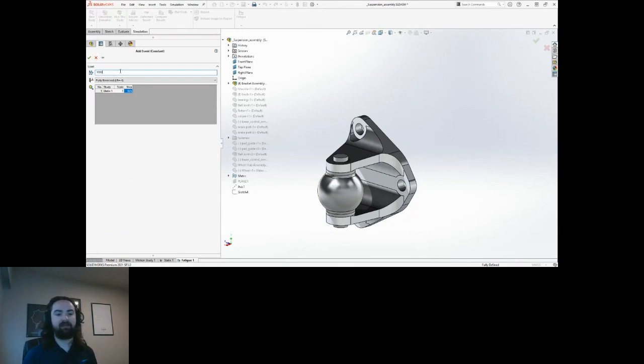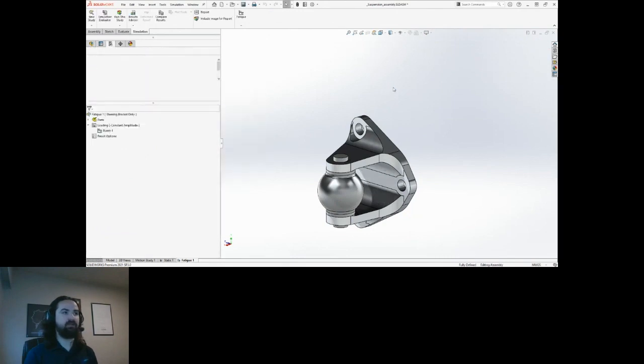And I did a bit of math here, and based on the number of corners at each track, the number of laps completed each race weekend, and the number of races during a full Formula One season, the steering bracket will have to undergo roughly 100,000 cycles. So I'll plug that value in, and that's all the information that is needed for this fatigue study. It's super basic to set up here. And so I can go ahead and run the study.